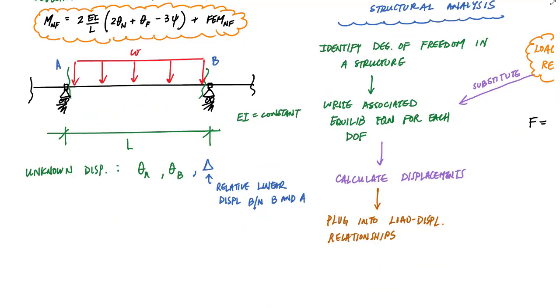All right, so since we're deriving a relationship here, we need some sort of sign convention. For the slope deflection equations, our sign convention is based on the direction of rotations. We'll say that any rotation associated with a clockwise motion is positive.